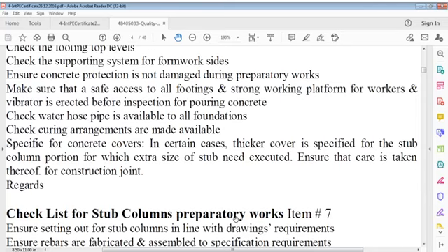And we know we have to provide a thicker cover in foundation, and for that, in that portion where stub columns are coming in, we can make the size of concrete more, so that the bar remains in position and the thicker cover is used in that stub portion, and the normal size of section starts from plinth level or grade level, you can say.